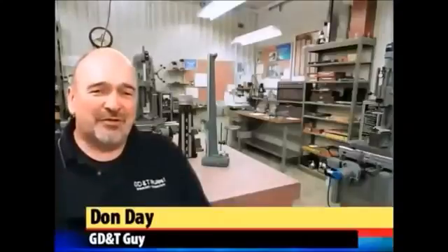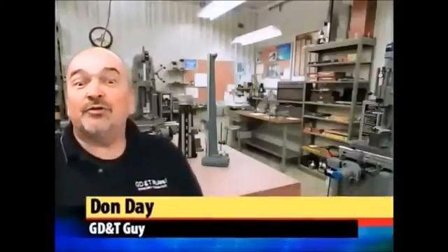Some folks continue to confuse dimensioning with tolerancing. They read the first section of the Y14.5 standard, which is on dimensioning, and ignore the later section, which shows how to tolerance the parts. Hopefully this tip will clear things up for some of these folks. On our premium site video, I have included a case study that shows a part that was made when the drawing did not make use of geometric tolerancing.